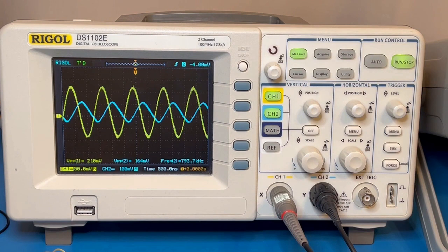Now the gain is actually below 1, so it's no longer amplifying the signal, and there's a significant phase shift at about 800 kilohertz. At this point, further increases in frequency will only lead to similarly lower gain below 1. Once the gain is below 1, the amplifier no longer serves as an amplifier, and therefore we don't usually look at what happens at frequencies above the gain of 1 point. But this gives you an idea of how the LM324 behaves over frequency in its configuration.